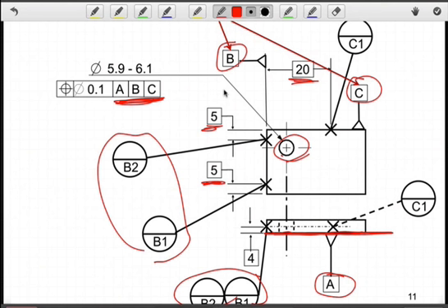So now I can determine these points with respect to a distance, and here again a distance, here again a distance from here, and then from the side you can see that we want a point in the midplane, and that's indicated by basic dimension here. We also do that for B. So we're being very specific about the points we're choosing to establish, first of all, the secondary datum reference, and that's going to be done with these 2 points. And we saw previously when we constructed the 3 planes, that's all we need are 2 points for the secondary.